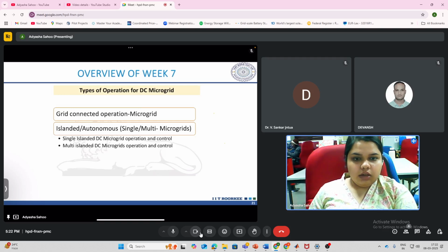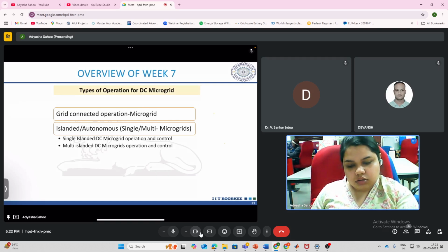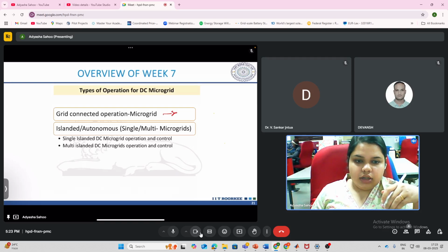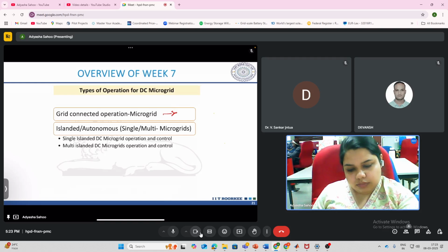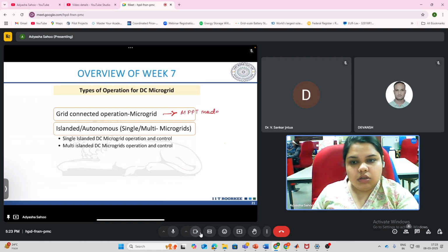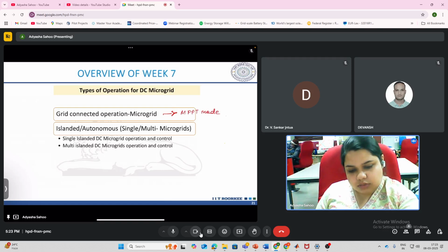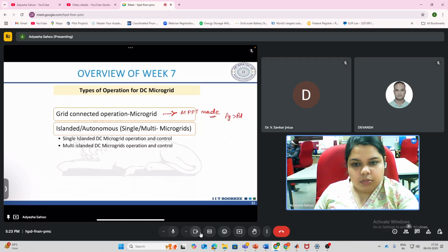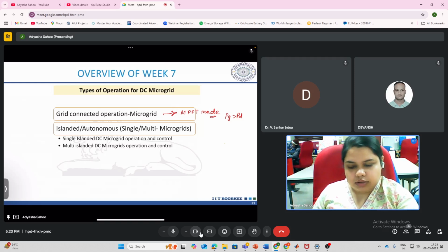If you have a grid connected microgrid, then the resources, let's say PV that you have with you, can always generate in the MPPT mode, because if your PG becomes greater than PD, you can inject this power back to the grid. So you can always operate in the MPPT mode to avoid any curtailment of your green resources.